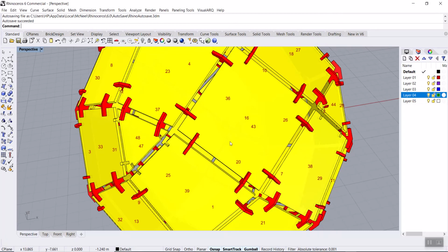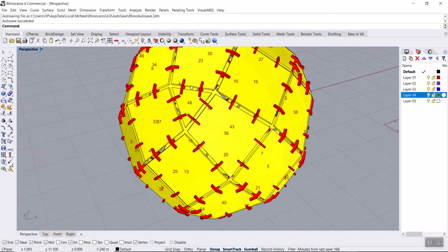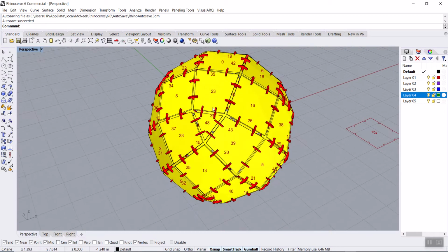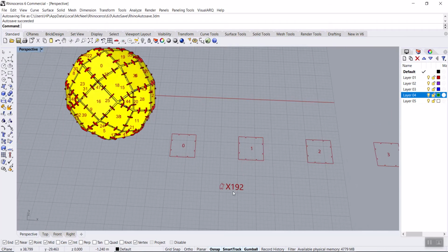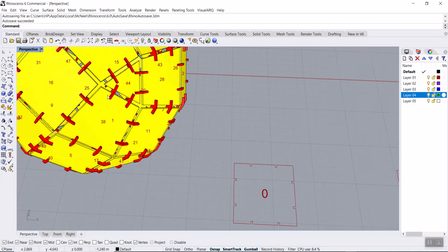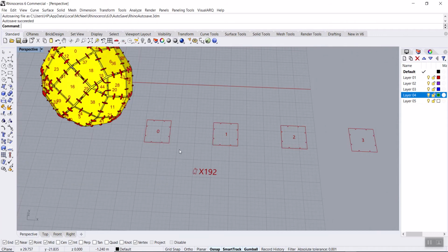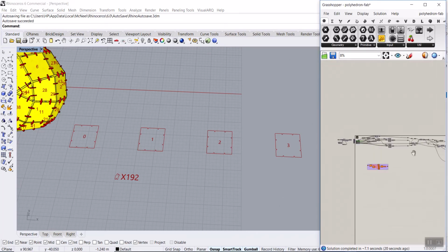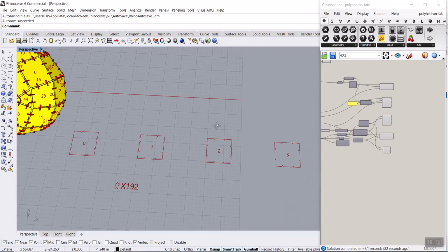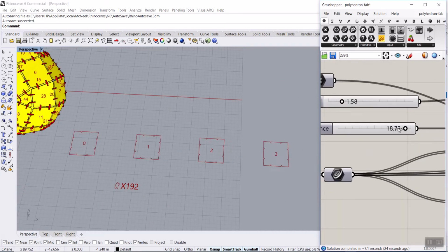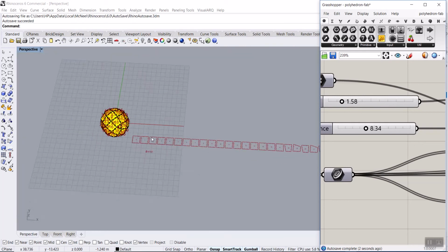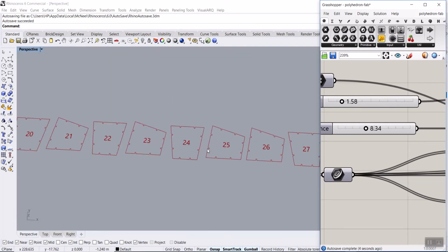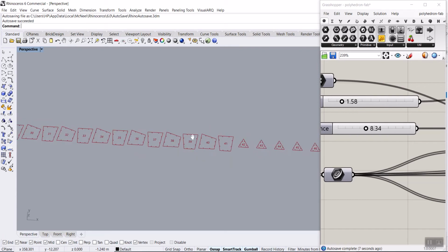Then you can also play with the thickness and those inputs. Okay, that's it. You can see that we can have the final results, and on the ground these are the numbers of the sections we need. All of them are the same because we're going to use a unique technique to extract the connections. And again, in the definition, we can go here, which I'm going to explain, and decrease the distance between these sections. Okay, and we have all of these sections that we want to fabricate.